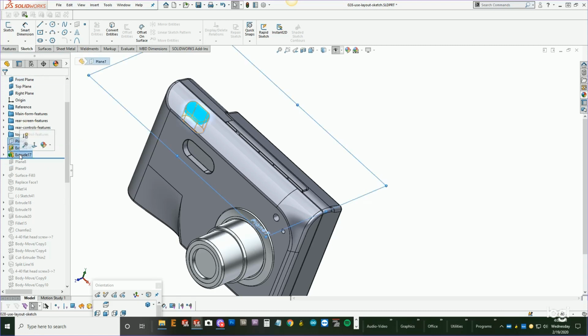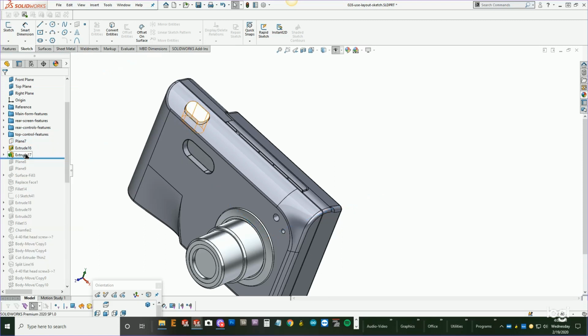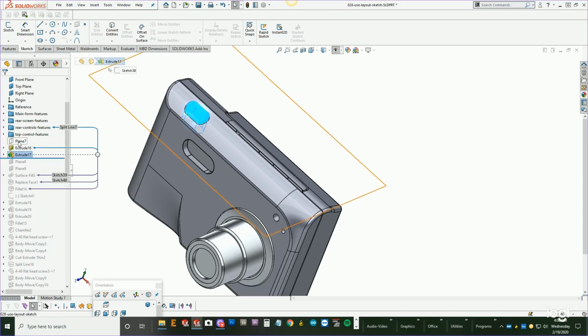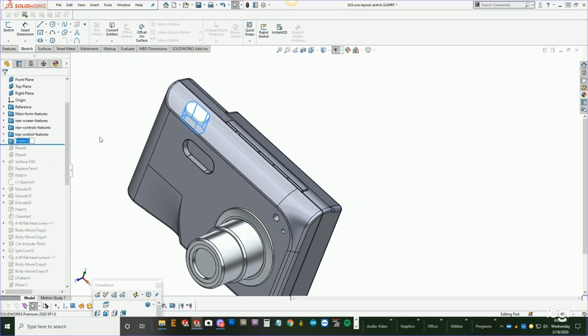And you can see that there's probably more details like a fillet and whatnot that is to be included with that. But for right now, I'll just folderize these three features, and then I can add to that folder. That's what's great about folders, is that once they're folderized, then you can drop other features in them that you find further down the tree, like what I showed earlier.